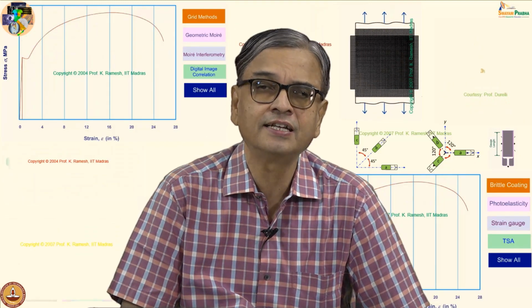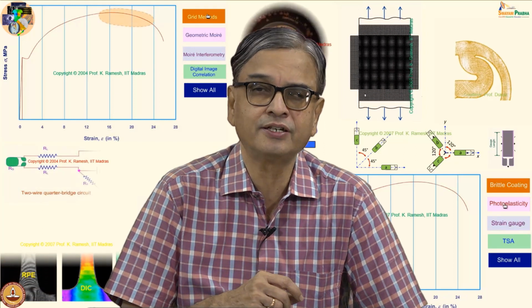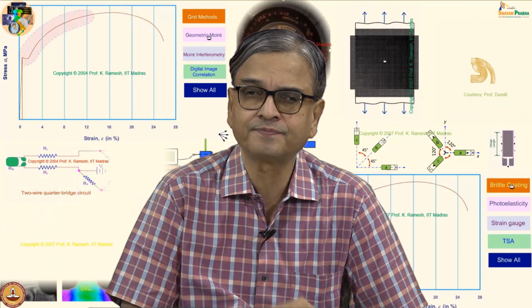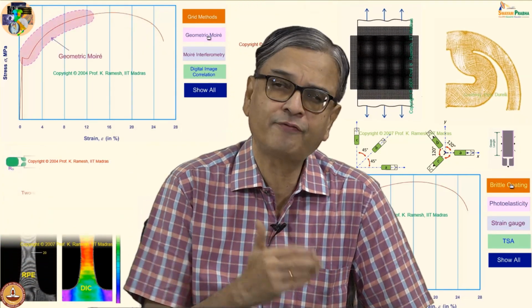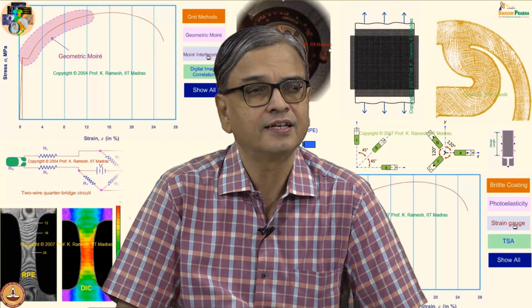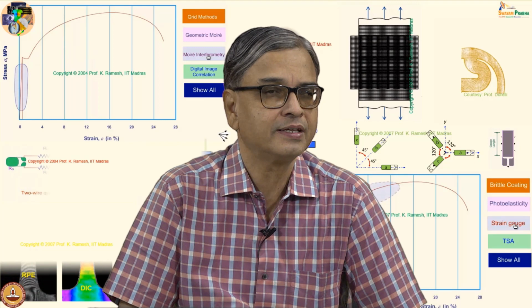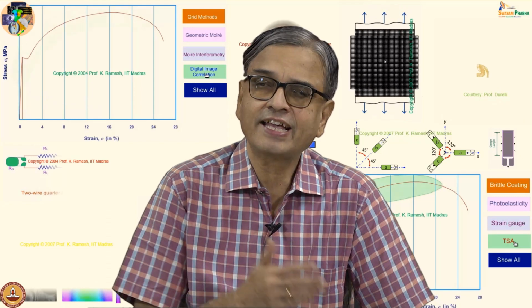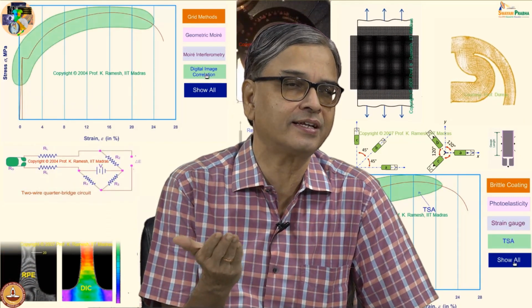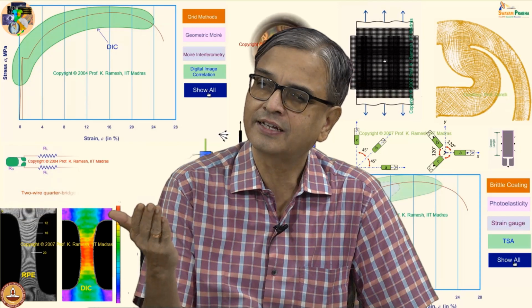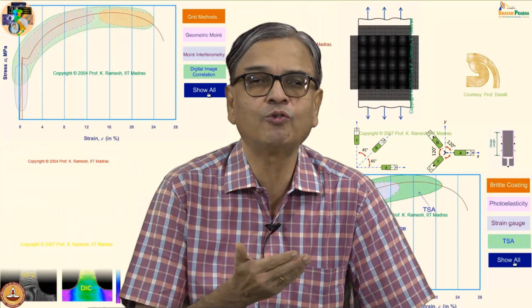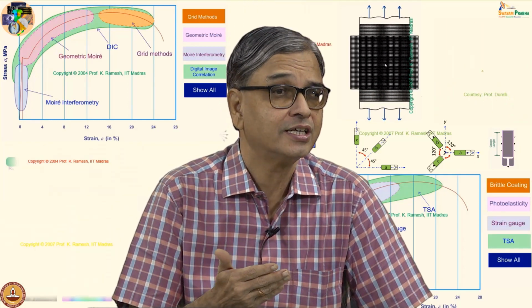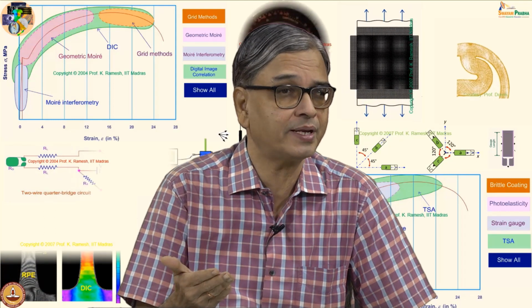So, you should recognize when we want to make strain measurement, you should be sensitive that we are going to measure very small quantity. And you have used a scale for measuring length. You have also used a vernier caliper. You have also used a screw gauge. You must have done it. And scale, you can measure 0.5 millimeter reasonably well. When you go to a vernier caliper, you can go down to 0.01 millimeter. When you go to screw gauge, you can go down to 0.001 millimeter.